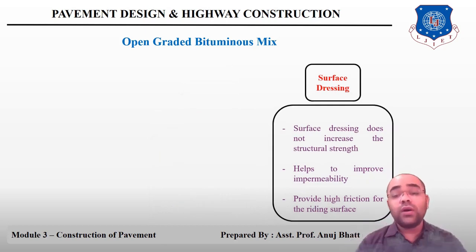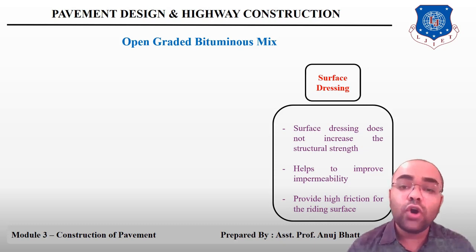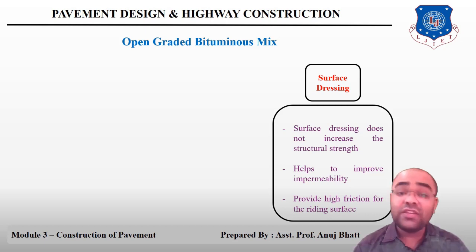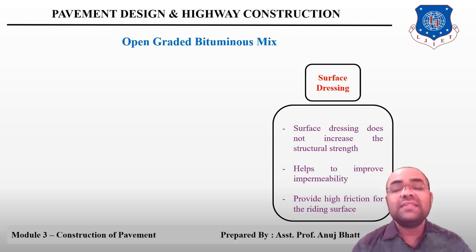The surface dressing work involves the process of spraying bitumen or bituminous binder or rapid setting cationic emulsion in 1 or 2 coats. This is applied over an aggregate layer of appropriate size and gradation. The grade of bitumen shall depend upon the climatic condition. The size of the aggregate shall depend upon the type of the surface on which it is being laid, and also on the traffic intensity.